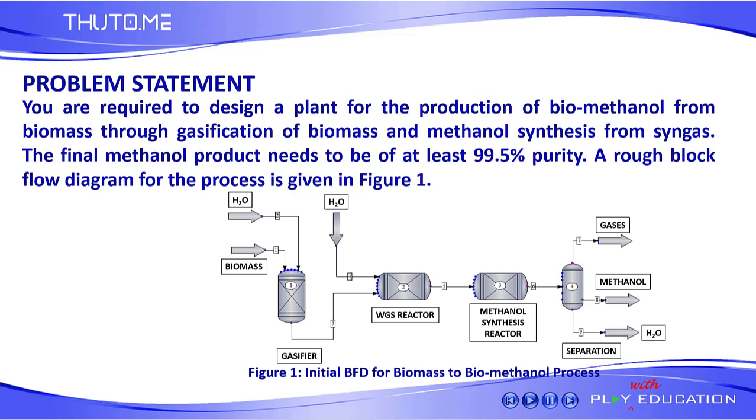This is not a process flow diagram. The process flow diagram will emerge from your design, but this is a simple concept to indicate to you of the possible process units. This block flow diagram will give us a starting point. Please note that as details emerge, the flow sheet will have pumps, compressors, heat exchangers, separators, recycles, and other units, as well as process layout schemes that will be dictated by the process synthesis procedure.